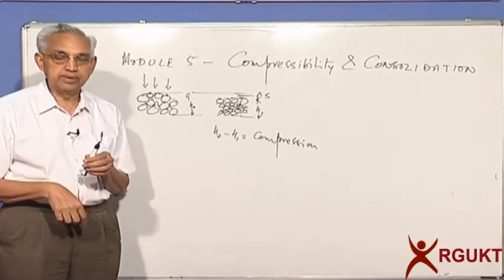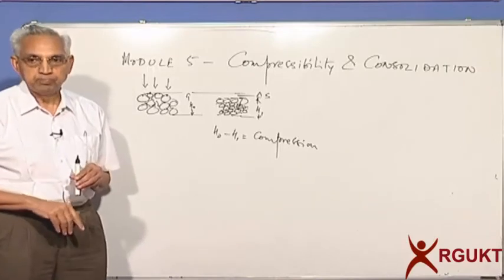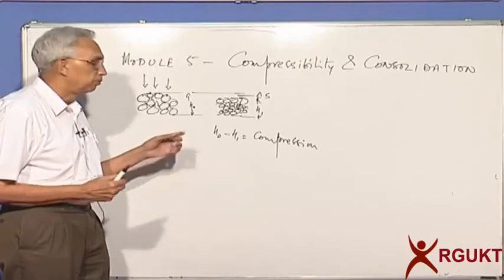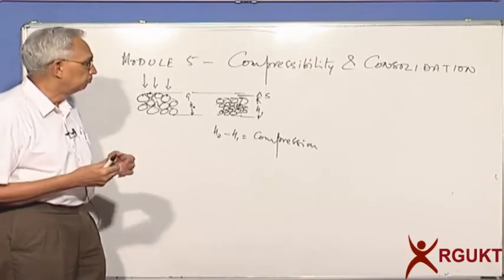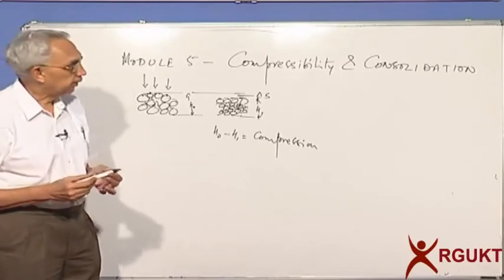So if you look at, even when you walk on the beach or if you are walking on a soft soil, your weight is enough to push the ground below, and your foot will sink into the ground. Why does it happen? Because when you are walking, you are transferring your weight onto the soil, and the grains will try to rearrange themselves. What are the possible ones?